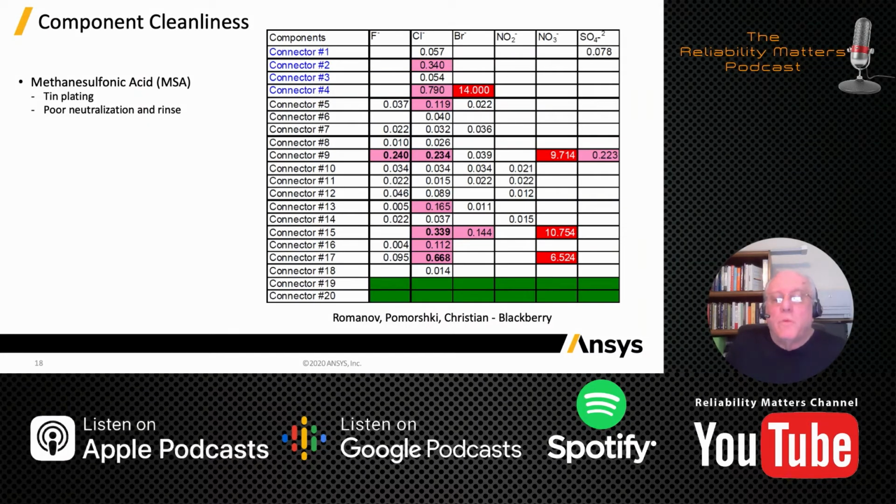So some work was done by Bev Christian and his team at Research in Motion and BlackBerry that they published a few years ago, where they looked at component cleanliness. In previous episodes of the Reliability Matters podcast, the guests have talked about one of the things that you need to be thinking about in terms of cleanliness and cleaning: if you make a decision not to clean, you're making a decision to leave all the contaminants in place that your boards and components arrive with.